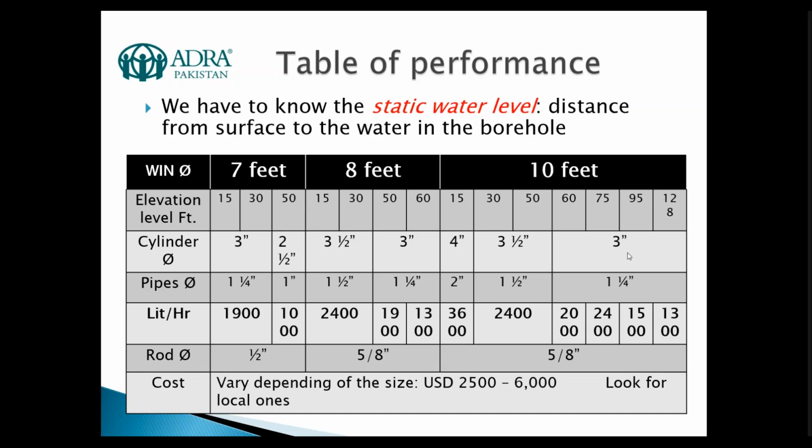And then we are using this fan or windmill, the 10 feet. You can see here in the table the level in feet of the elevation of the water. If you have water from 15 feet, 30 feet, you can use an 8 feet. If you have less than that, you can use a smaller one. That will work very well. But if you have deeper and deeper, you can use bigger ones. And we can see that up to 128, even up to 150 feet, you can use this 10 feet propeller.